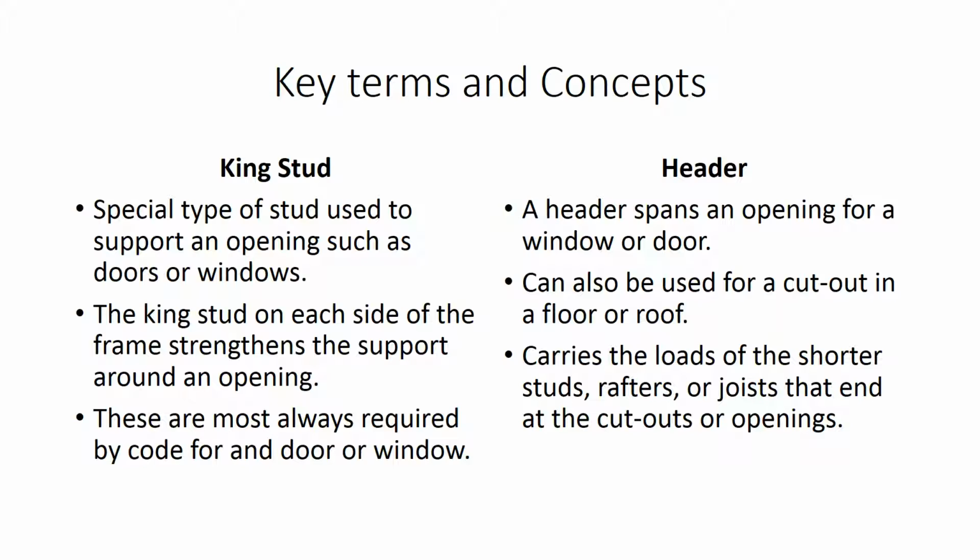A header spans an opening for a window or door. A header can also be used for a cutout in the floor or roof. A header carries the loads of the shorter studs, rafters, or joists that end at the cutouts or openings.